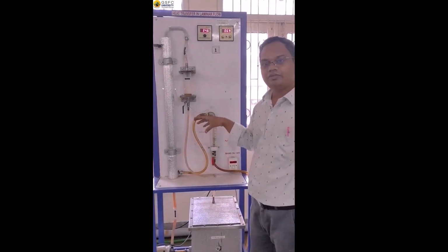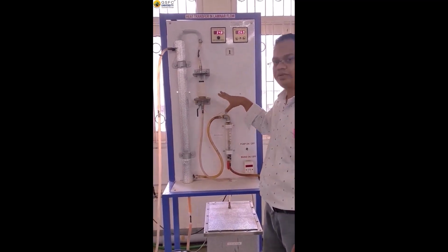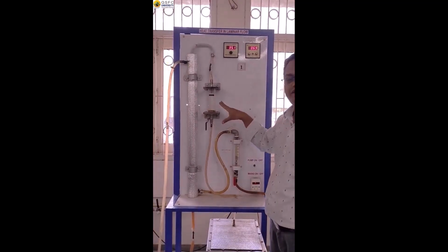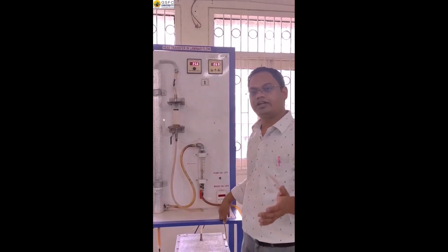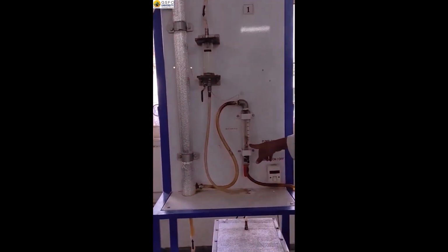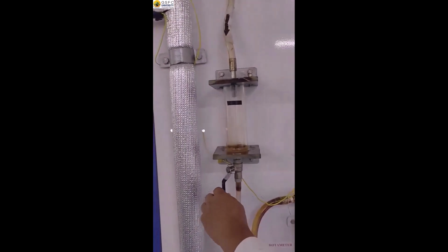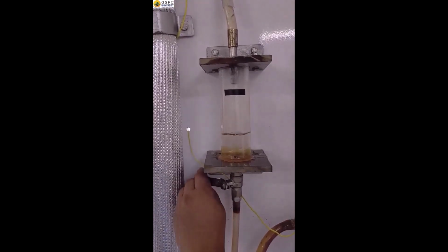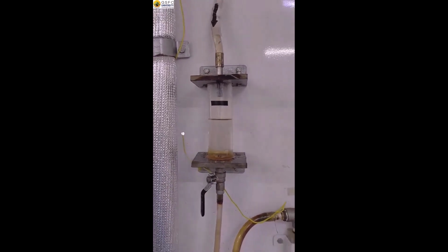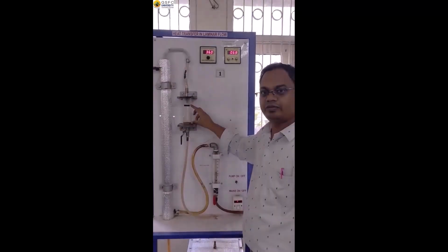Before measuring the volumetric flow rate, it is always advised to wait for some time so that the system can reach the steady state. Otherwise, due to the temperature difference, there will be a significant difference in the viscosity that can affect the flow rate. Note down the volumetric flow rate of the cold fluid. Then stop this. Note down the time until this place. Then again open this. Repeat this experiment at least 3-4 times so that you can have an average value plus error.